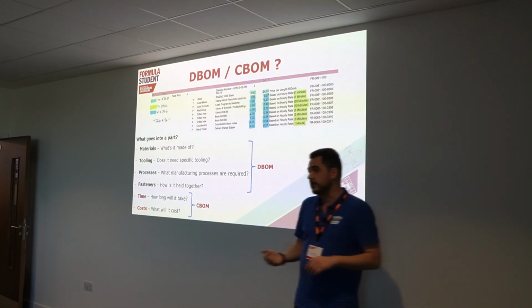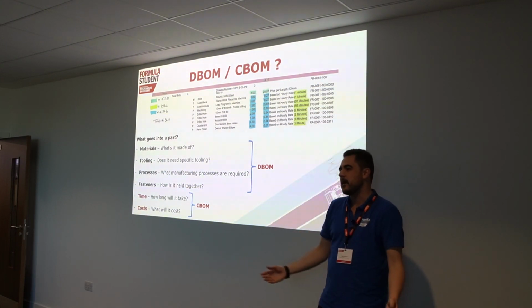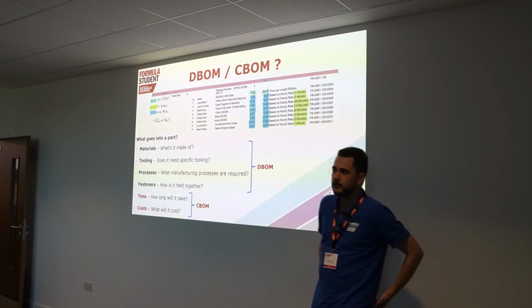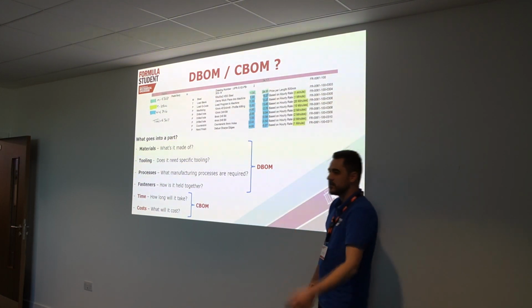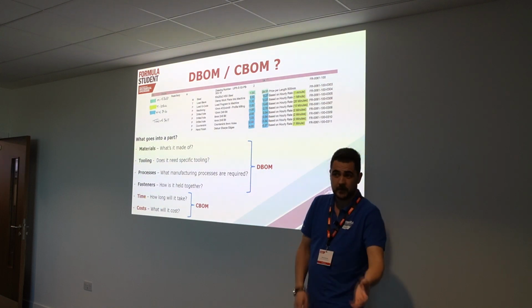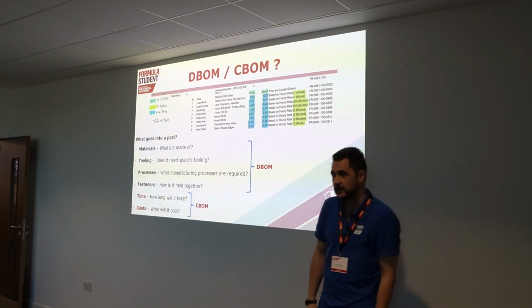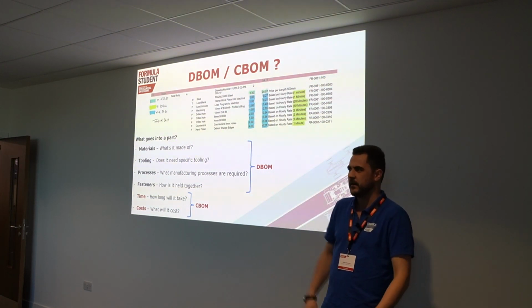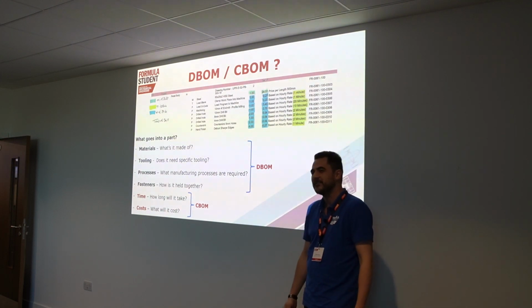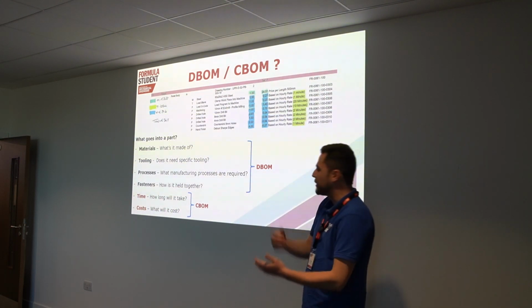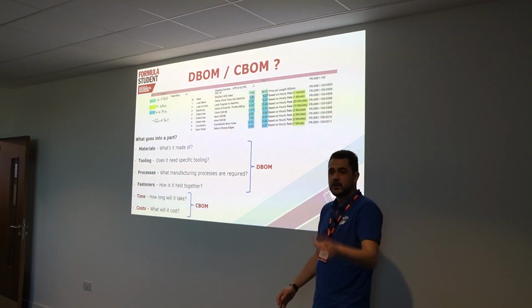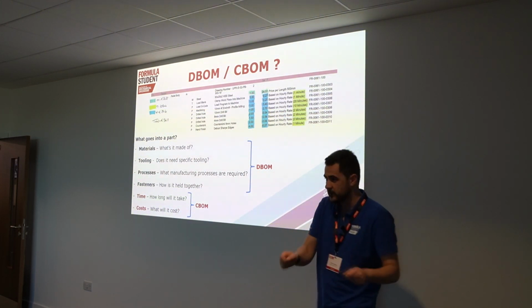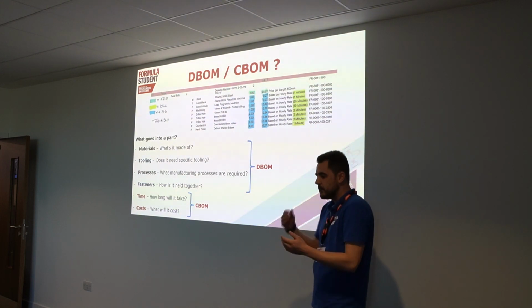When you're looking at tooling, chassis are a big one. The amount of teams that go, oh yeah, we'll just weld it up. Oh right, did you? You had no tooling. Or composite one. Okay, did you do pattern mold? Did you straight off the pattern? How many parts can you get off that pattern? Oh no, we just laid it up. Oh, you laid it up over nothing. Right, okay. You didn't, but all right. Make sure you've got every piece of tooling you use. If you're doing any composites part, 3D printed jigs. If you're putting trim lines on it, or if you're putting drill holes, anything like that, put it in there.